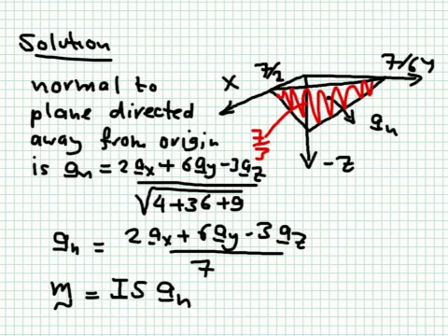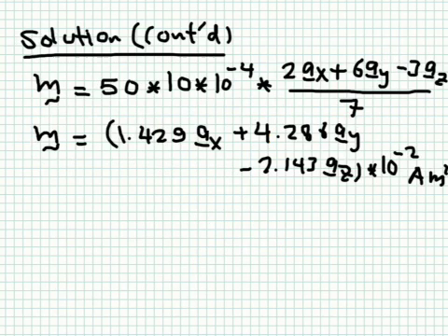And again, it can be rectangular, it can be square, it can be circular, and for all of them, this is the definition of the magnetic moment. So we put all these numbers together. This is the value of the current, this is I. The area is 10 centimeters squared, so you multiply by 10 to the minus 4 to convert it to meters squared. And then this is the unit normal.